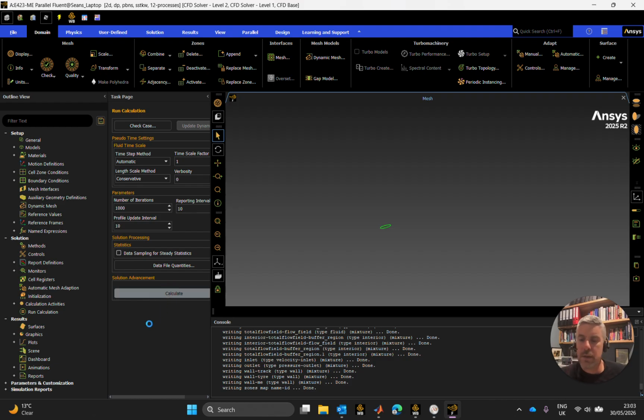Let's go. Let's hit calculate and see what we are going to get back with here. I feel better now when I see the residuals come up and see them moving. And then what we'll do is I will hit pause because this could take a wee bit of time. Albeit I wouldn't expect that it would take more than maybe half an hour for this. We do about 800,000 elements on it. The meshing is pretty good, so hopefully it will find itself converging relatively fast.